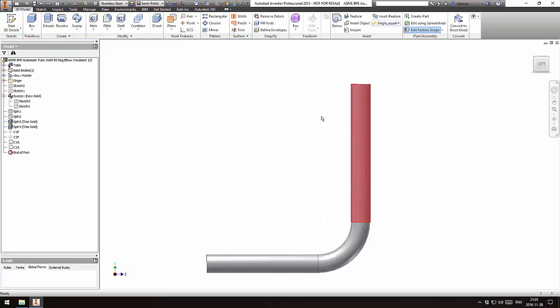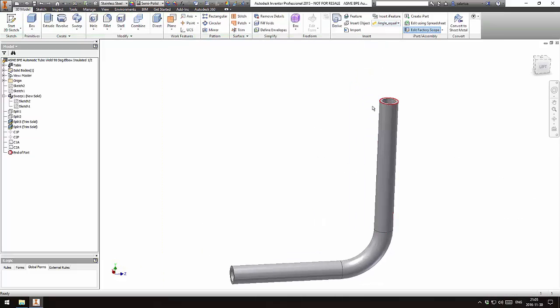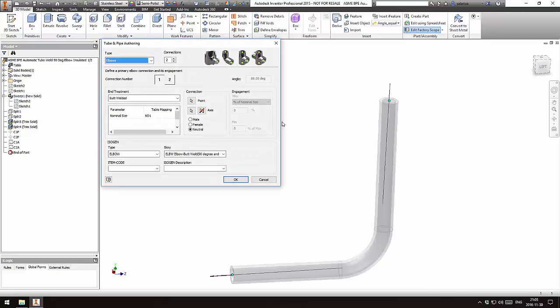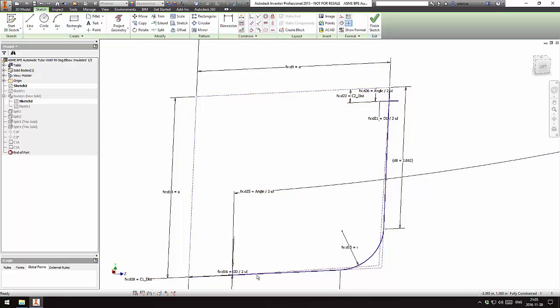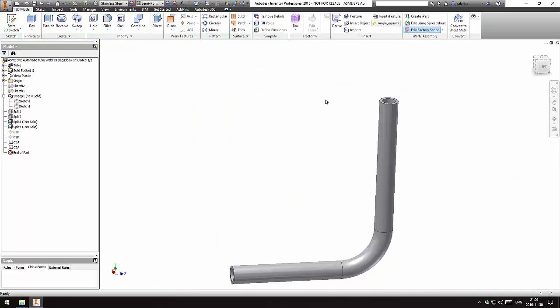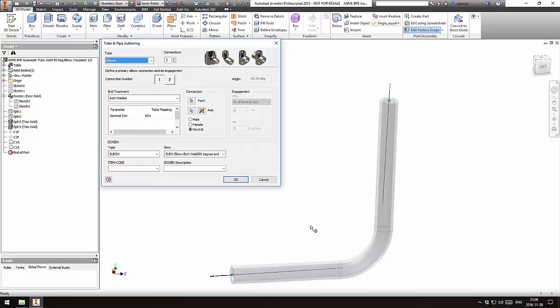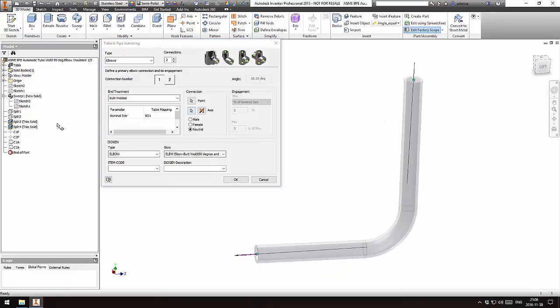I don't recommend that you use the face for authoring, because when you use the face, keep in mind that the split, you could actually end up splitting it right there past the bending line, and this circular face will not be circular anymore. So I recommend that you go through the process of creating a point and a line, and then in the author window dialog you actually select the axis as being your axis.